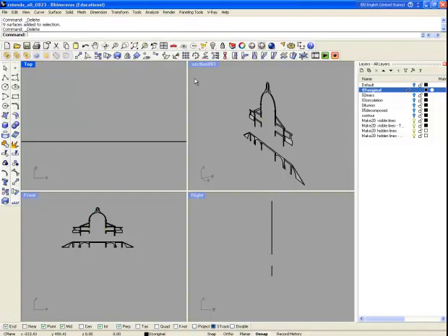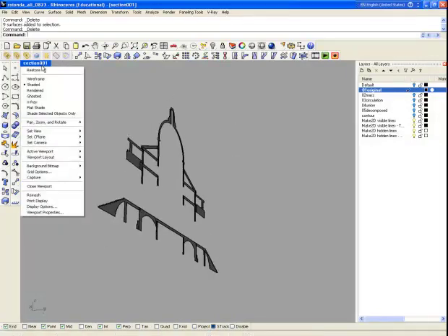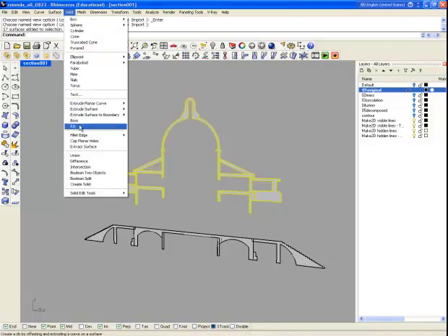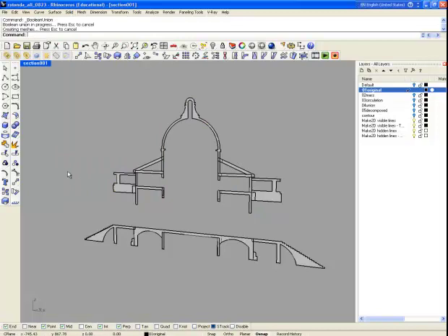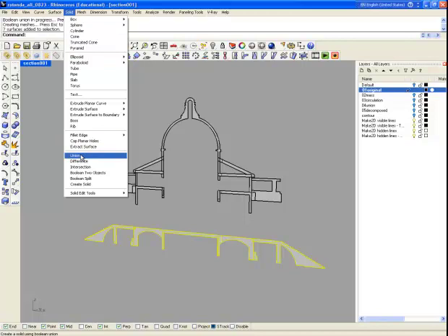Okay, looks okay. And then go back to section 001. As we already just changed this view, we want to go back to our original section 001 view, in order to fix the angle and match the angle to the previous section 001. So over here, what we need to do is union those surfaces first. So these surfaces, union them, okay, and then these surfaces, union them. Under Solid, you can find the union command.